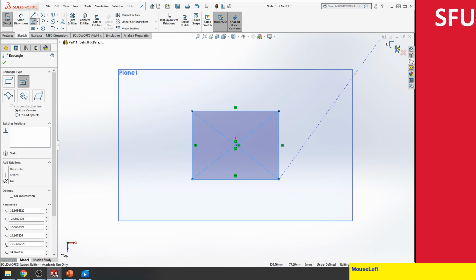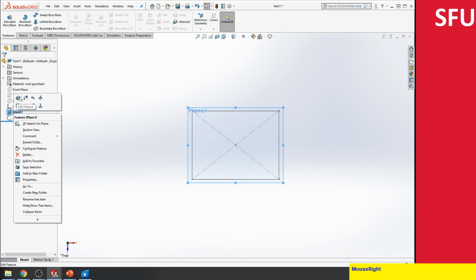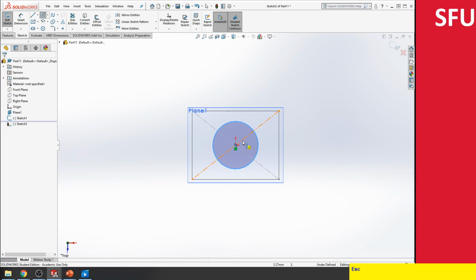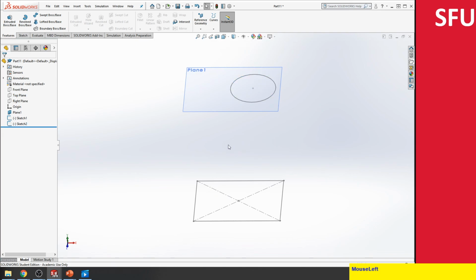We're going to say exit. Then on the other plane that we created, we're going to create a circle. If you want, you can offset the circle. Then say exit. If you go to this view, or press Control 7, you'll see how it is.